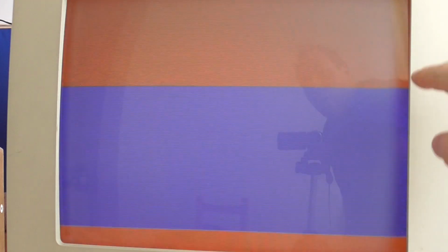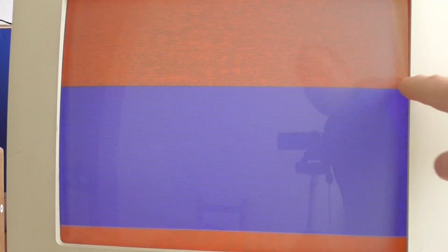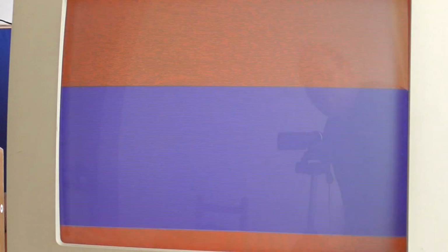And so they'll be out of sync for a while until finally a tooth matches up because it's the right size, and then from then on everything will be in sync. So you can see that I never quite get in sync here. It's very, very close, but this last little bit of the line here shows some flicker due to the fact that by this stage things are still a little bit out of sync.